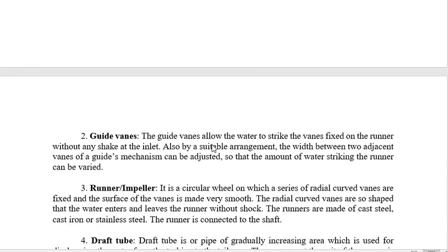Then we have the guide fans. The guide fans allow the water to strike the fans fixed on the runner without any shock at the inlet. Also, by a suitable arrangement, the width between the adjacent fans of the guide mechanism can be adjusted so that the amount of water striking the runner can be varied.